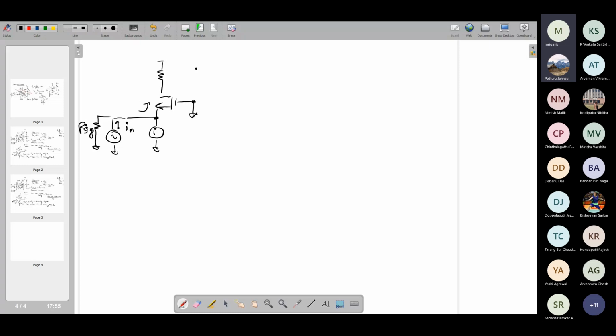So what is the input capacitance? In this case, what is going to contribute to the input capacitance? You can think of this. Yeah, so this current source will also be like a real current source, of course. So assuming that this is also like a transistor, the first thing is for M1 you have the CGS, because the gate is anyway grounded, so there is no Miller effect because of CGS.